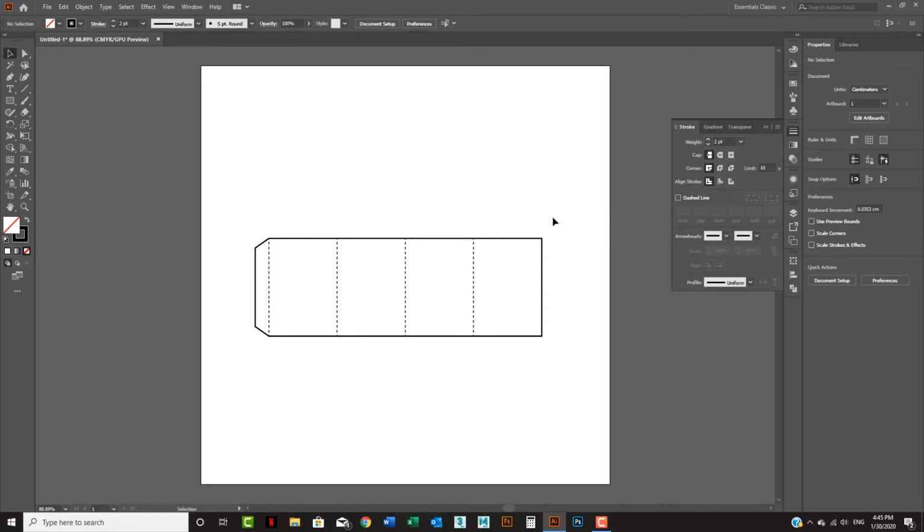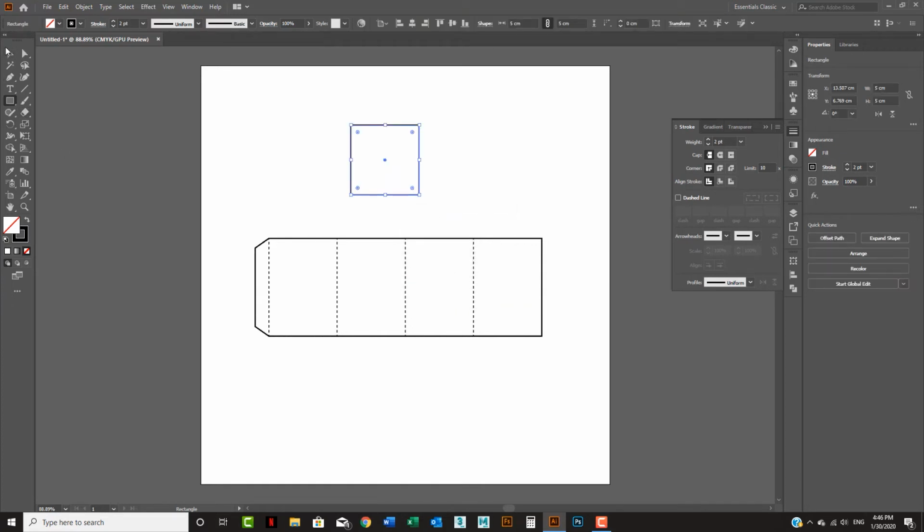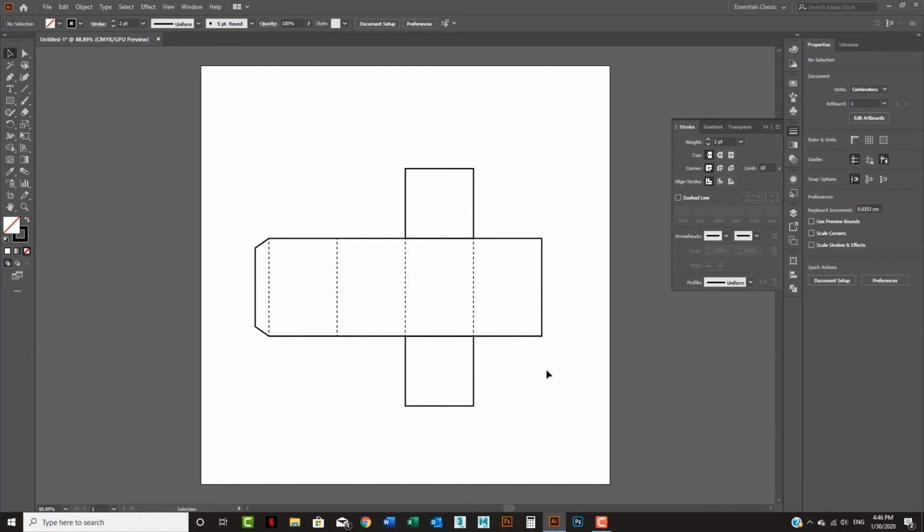to cap and the dust tab and all those things that we already talked about in class. Because my box, especially in the top view, is the square shape, so I need 2 more boxes. I'm going to use this one click. I'm going to make it 5 by 5 and press OK. I'm going to move this small, let's say here. Then I'm going to make another one in here. Again, hold Shift and Alt. So I have both caps that I have to close.